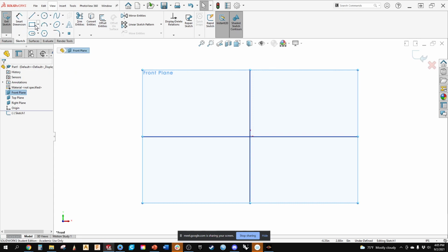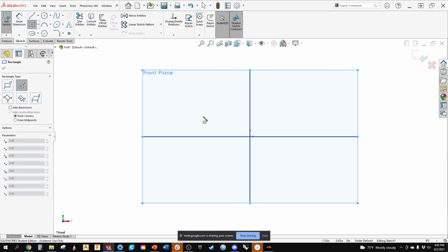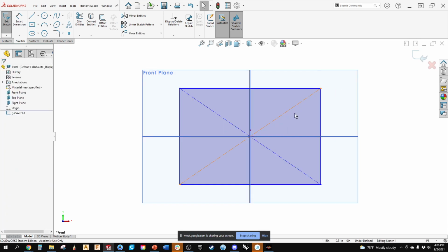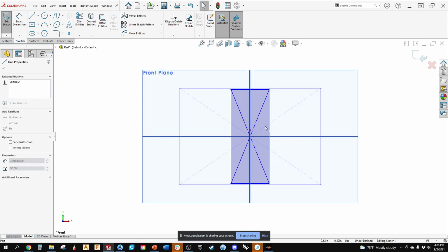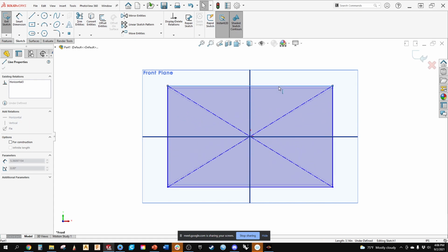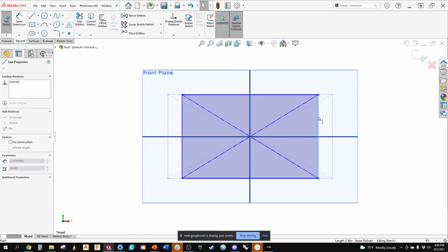So for this, again, we've talked about it before. Under the sketch commands, you can see where I've got a rectangle, and I've got so many different options for how I want to build it. Now, center, if you want to lock that center of that rectangle, it's going to create that relationship right to the middle, the coincident, so that I can then go this way. And the nice thing about that is if I adjust it, it does it via mirror. Even so I can just kind of push, pull, get the size right.